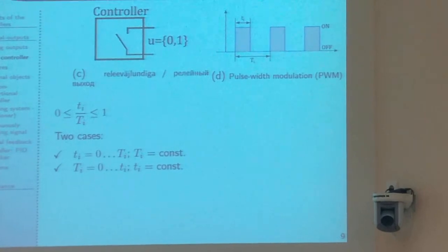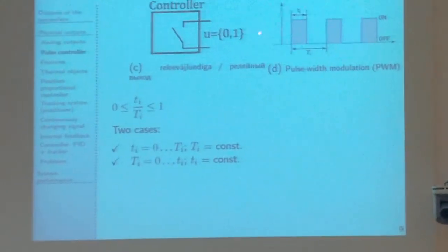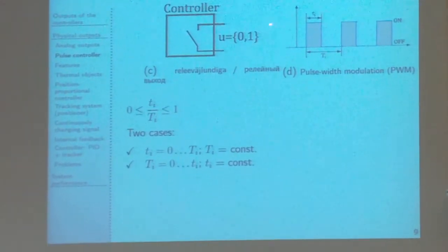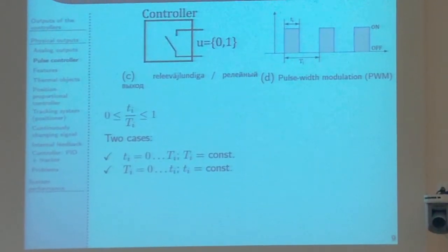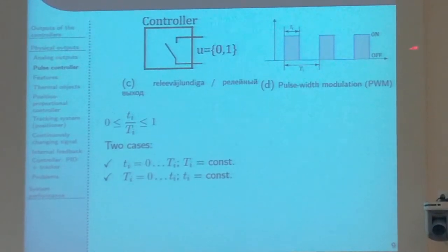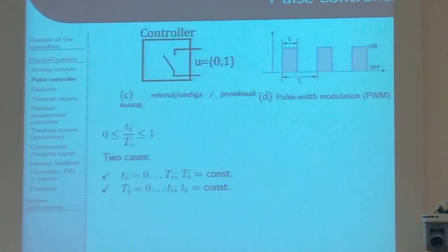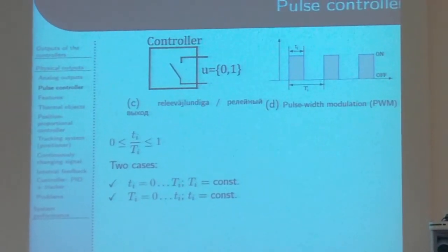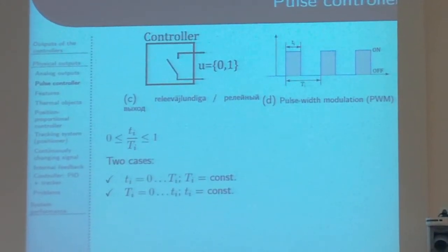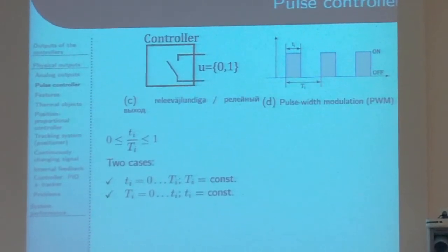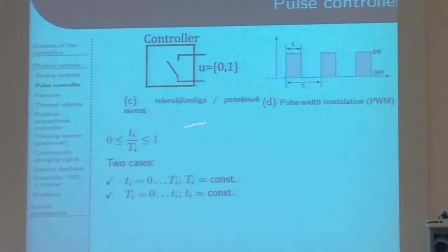During these 5 seconds we observe the relay output of the controller and manage the width of this pulse. But there are some other types of controllers where we can manage this parameter, but the pulse width will be constant. For that matter, please always check the vendor specification, where you can see and set the right characteristics.